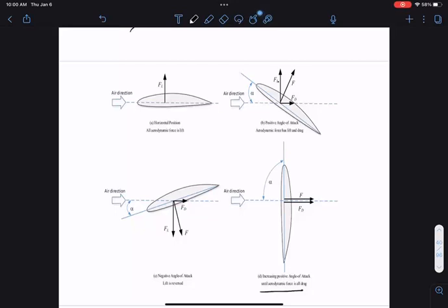If there was ever excess load, is rotational speed ever a concern? Yes. So load is relatively constant. The grid always balances generation versus load. There is never excess load in the grid that's not being served. So what you care about is if the wind speed suddenly picks up to be very high. There is not much load I can dump the power from the wind turbine to, because the load is being served by something else. To dump the power from the wind turbine to a load, something else has to generate less. That's actually a very hard problem to solve, and that's one challenge to operate a wind turbine.